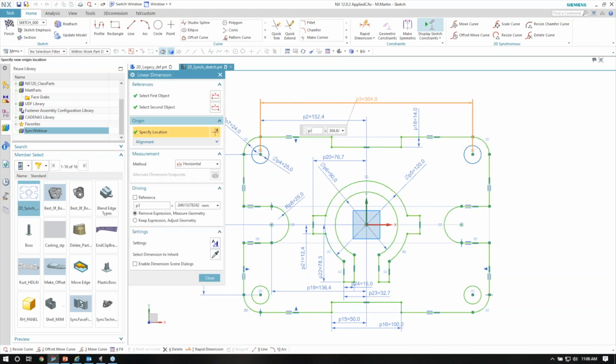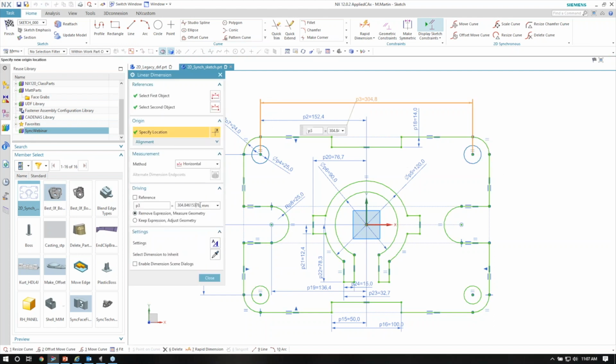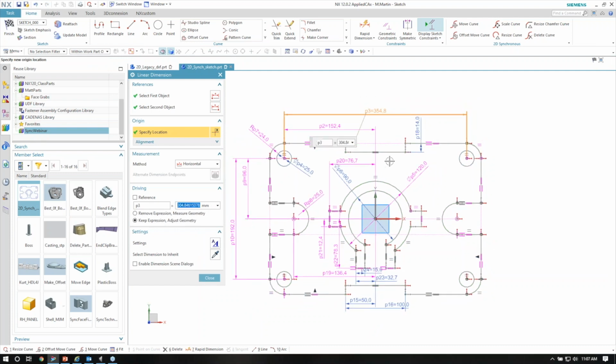I'm going to go to the end of the dimension and just add in plus 75 divided by 2, and it's not playing nice. I see some things that are not operating properly. Go ahead and close that. I'll Control Z and bring that back. Maybe I can try it a different way. Maybe I just say plus 50, see if I can get it to bump out, and then I get conflicting constraints. And it's just telling me that there's an overconstraint condition.